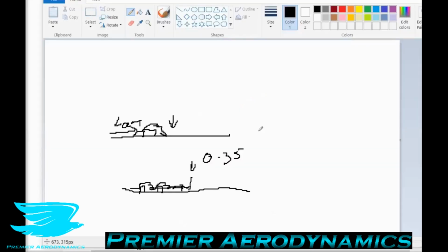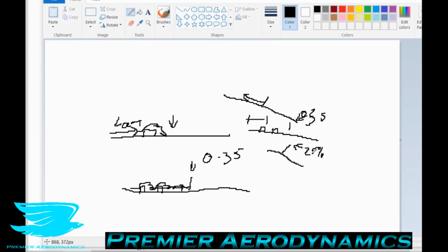So what they're referencing here is, as you have an airfoil or any surface really, as you continually pitch it at a higher angle of attack, the boundary layer, the LSB will move upstream. So if we had the airfoil at 4 degrees angle of attack, the LSB we know started at 0.35 downstream from the leading edge, 35% downstream from the leading edge. So these trips at 10% and 70% performed in a certain way. Now, if we increase the angle of attack to 6 degrees, the LSB will now be at a further upstream location, maybe let's say 25% downstream from the leading edge, sorry. So now these trips are, relatively speaking, much closer to the LSB formation.